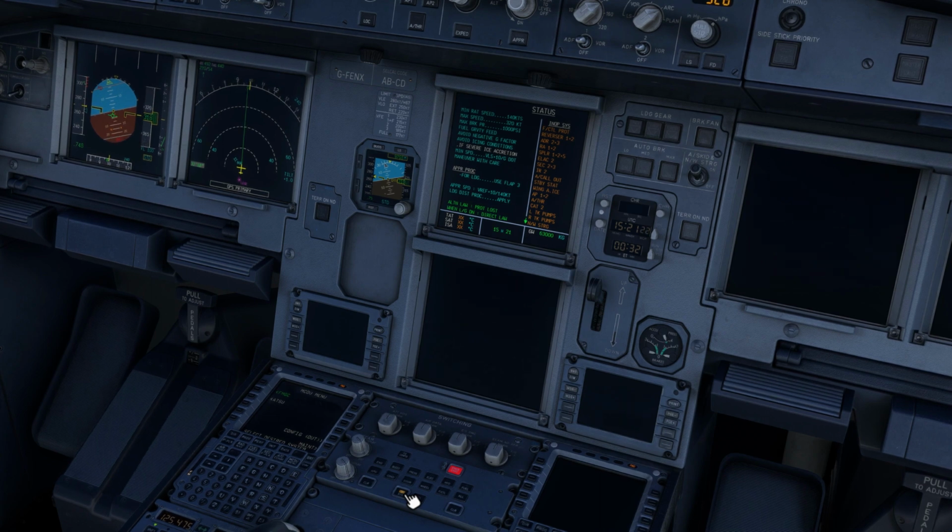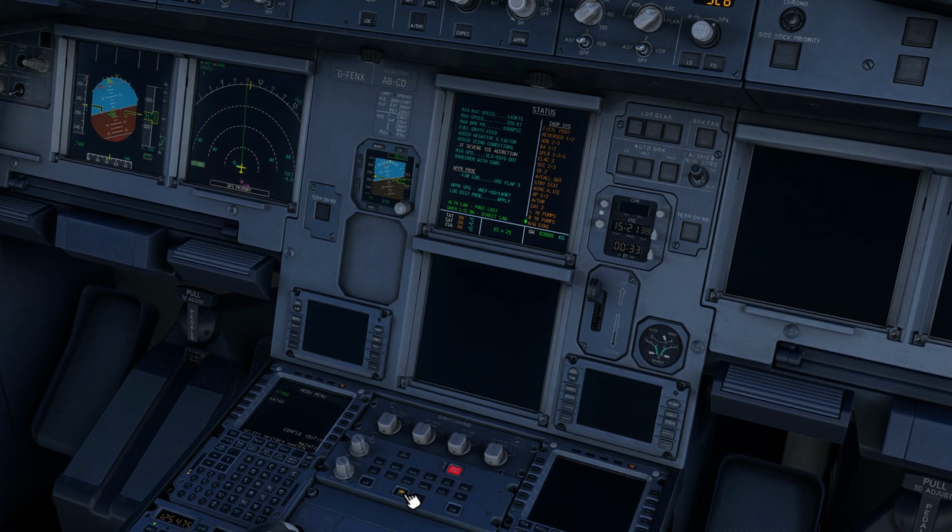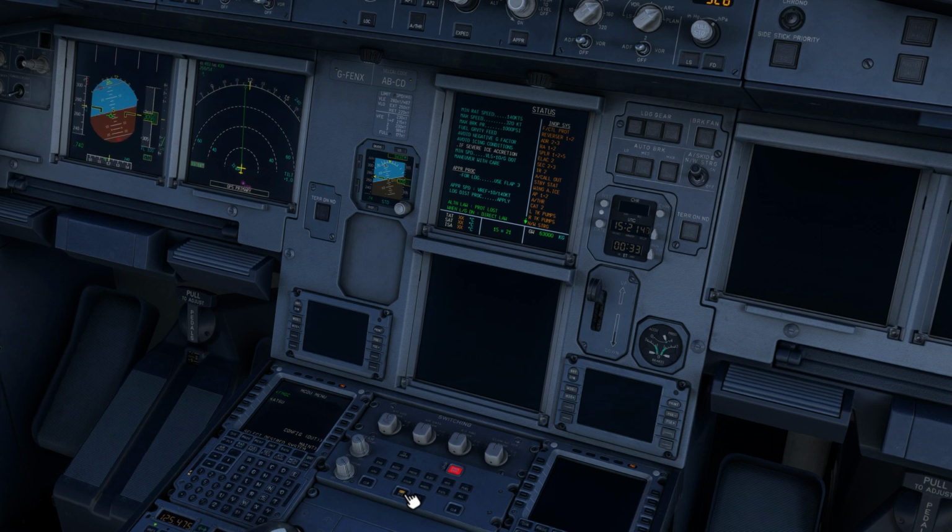Inoperative systems are flight control protections, reverse 1 and 2, ADR 2 and 3. RA 1 and 2. Spoiler 1, 2 and 5. ELAC 2. SEC 2 and 3. IR 2. Auto call out. Standby static system, wing anti-ice, autopilots 1 and 2. Auto thrust, Cat 2, left and right tank pumps, and nose wheel steering.